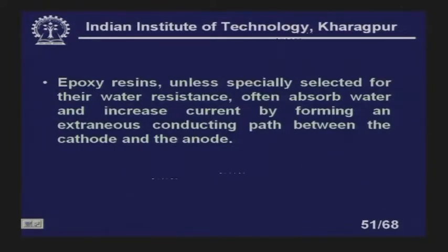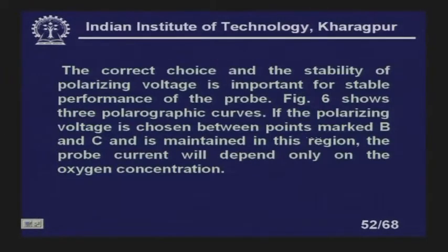Epoxy resins, unless specially selected for their water resistance, often absorb water and increase current by forming an external conducting path between the cathode and the anode. This is again a problem, because usually we use resins to hold the cathode and anode in these systems.